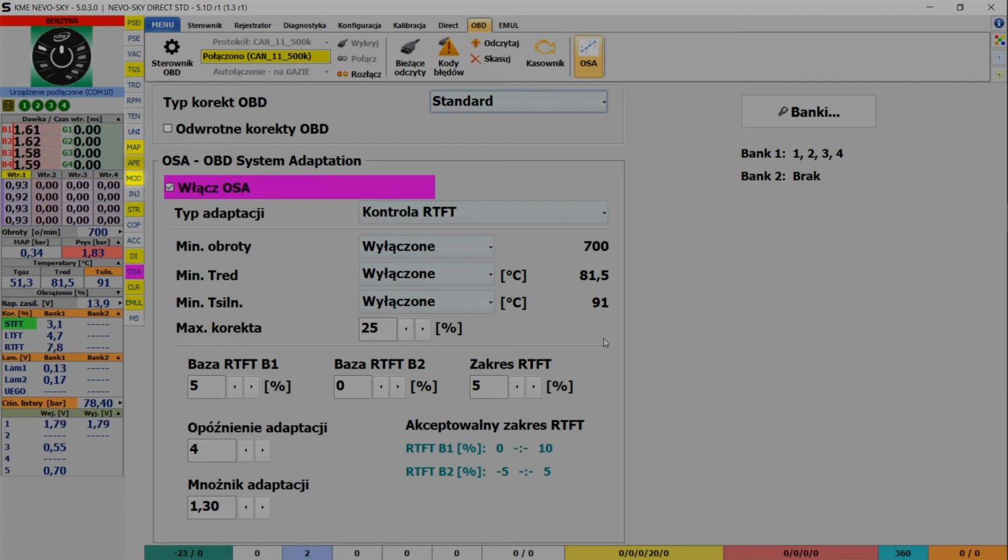Correction map. Calibration of the model. Correction for injectors. The enabled correction is also visualized when reading gas injectors. Switching strategy to gasoline with automatic return to gas. Cut-off mechanism. Correction for acceleration, indirect injection only. Direct injection, correction when changing the injection system, indirect injection only. Adaptation according to MOS maps, indirect injection only. OBD-OS adaptation, OBD error eraser.